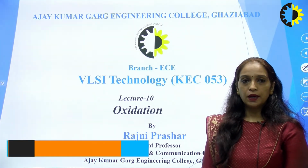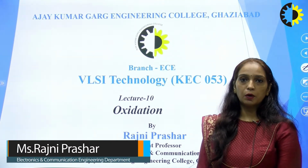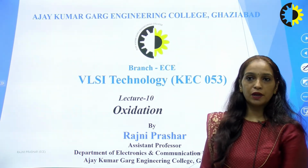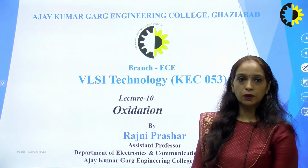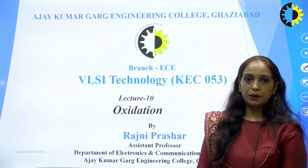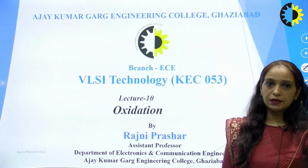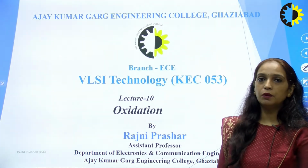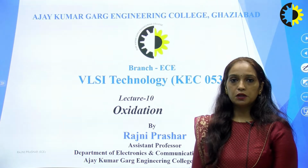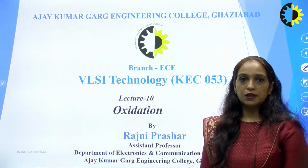In the last few lectures we have covered the epitaxial process: how epitaxy is done, what the types of epitaxy are, how we can grow the epitaxial layer, and how those epitaxial layers are evaluated, that is by liquid phase epitaxy, vapor phase epitaxy and molecular beam epitaxy. With the help of those three processes we can have the epitaxial layer, which acts as a buried layer for the IC fabrication technology.